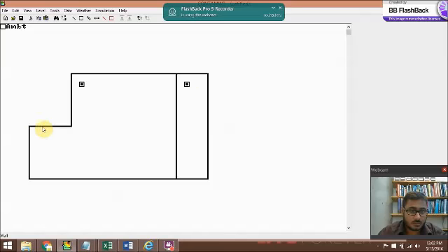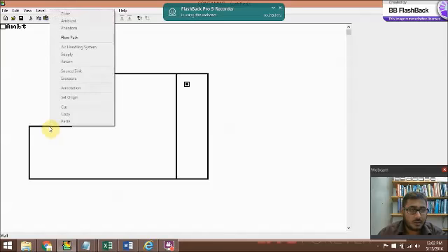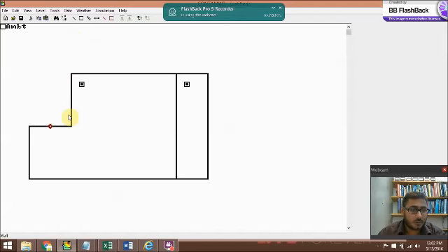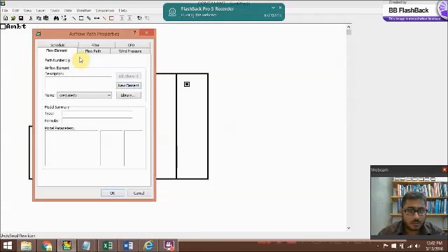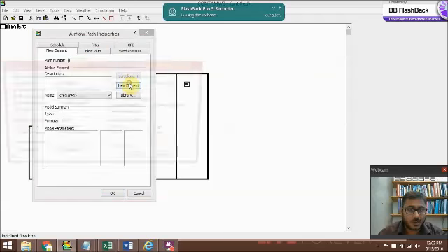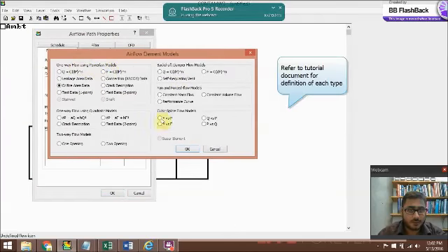So to create a flow component, you have to click anywhere on the wall and right click it for a flow path. So this would determine your flow in this wall, and double click to open it. You have to first do a new element, and there are different airflow elements and different methods to determine what kind of airflow you want.